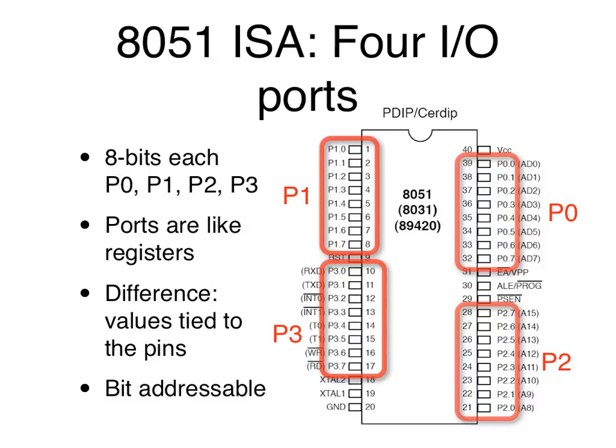Breadboards are these prototyping boards, usually white, with a few rows of holes, and then you push one of these in, and then they connect, right, on two sides. And these will have a little notch on the top to tell you which way is up. So the little dip on the top indicates that's the way it's up. And then the power and ground are always on opposite corners. Right? The power is always upper right, ground always lower left. At least within the DIP package.